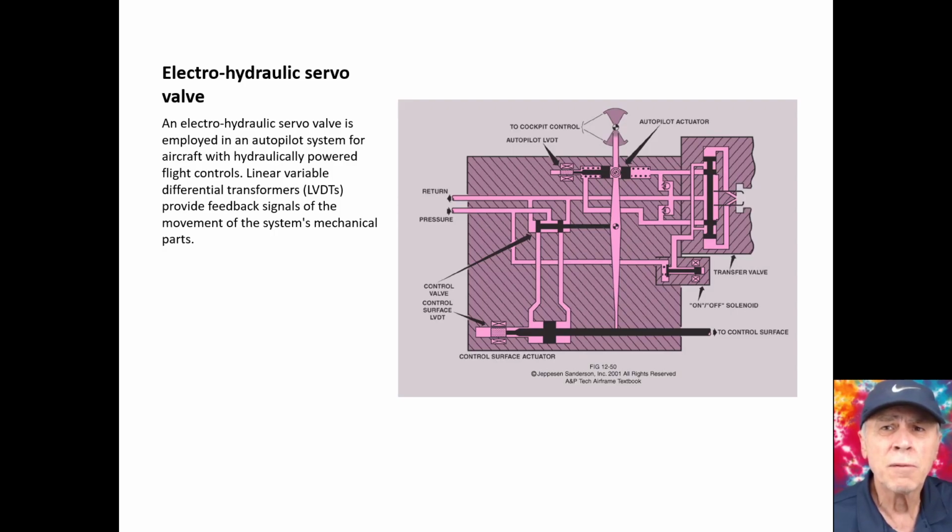Electrohydraulic. Basically, there's hydraulic elements, which basically is shown quickly. It looks like the black in the illustrations. And depending on the forces on either side, there's a way to move the system by use of hydraulic fluids, in effect. The control surface actuator, that's probably more the piston that actually moves the system.